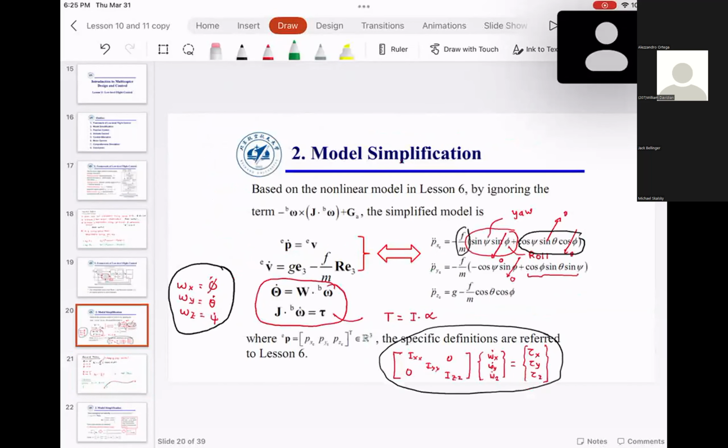So that way, now when your theta is equal to 0 and your phi is equal to 0, can you see that this becomes only 1? What this means is, your upward or downward acceleration is just a function of the thrust that is generated by the motors. So increase the speed, it will go up. Decrease the speed, it will go down. Everyone understood this?